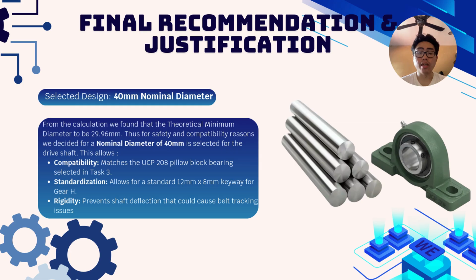Finally, we have selected a 40 millimeter nominal diameter for the drive shaft. While 30 millimeter is mathematically safe, the 40 millimeter choice is a practical engineering decision for three main reasons.